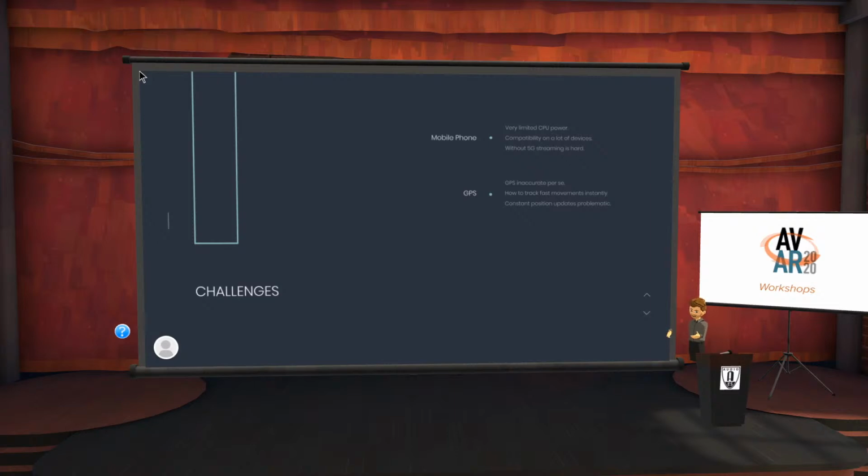And we tried to experiment with all kinds of approaches, like: if the accelerometer recognizes a movement above a certain threshold, then update the GPS position. Without that, please leave it. We also tried to use the accelerometer data to predict the direction where somebody is going. With these predictions, we got into the Kalman filter stuff.